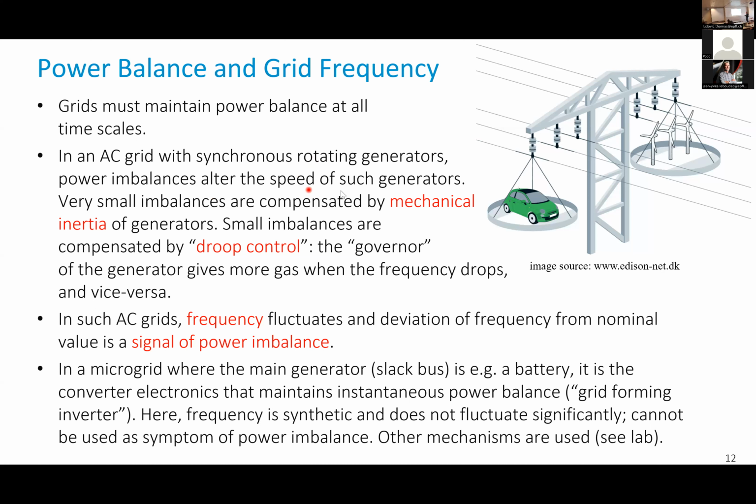So there are small imbalances that translate into small frequency differences. You've seen in the previous modules how to estimate the frequency with a PMU. You see that it varies all the time. But there is a balancing system, which is the mechanical inertia. If you pull more on a big rotating mass, then it slows down, but by slowing down, it returns some of the mechanical energy that it had when it was turning. That energy is delivered when you slow it down, which balances in the short term. There is a balancing effect of these big rotating masses, which stabilizes the grid.